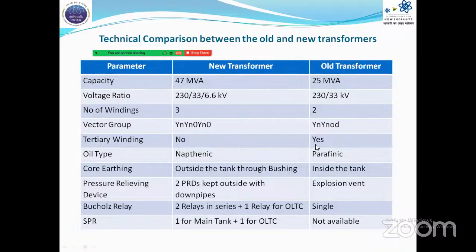Because flux density is more, to maintain the flux, because we know flux phi is equal to Bm into A. To maintain that flux constant and to minimize the area of the core, flux density is kept at a higher level, and the transformer is operated in the knee region of the magnetic characteristics.